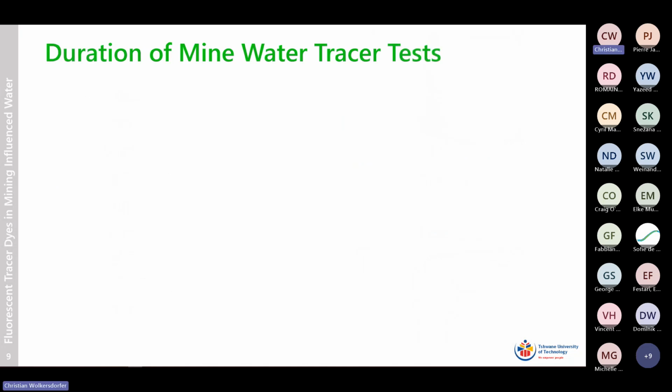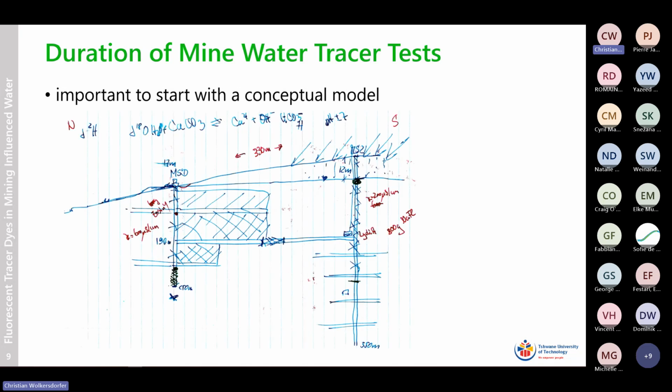Duration of mine water tracer tests. First of all, it is important for a mine water tracer test to start with a conceptual model. And usually we draw this by hand. This is a Finnish mine with 2 shafts that is connected mainly on one level. You can see that it's very important to understand how the water is flowing inside the mine and what we have to expect, also, for example, to use the right amount of tracer.